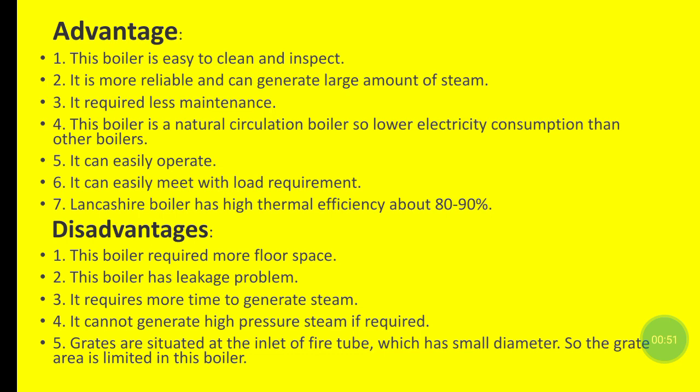Now the disadvantages. This boiler requires more floor space. This boiler has leakage problems. It requires more time to generate steam. It cannot generate high pressure steam if required. Grates are situated at the inlet of the tube which has a small diameter, so the grate area is limited in the boiler. So friends, here we have discussed the working and the advantages and the disadvantages of the